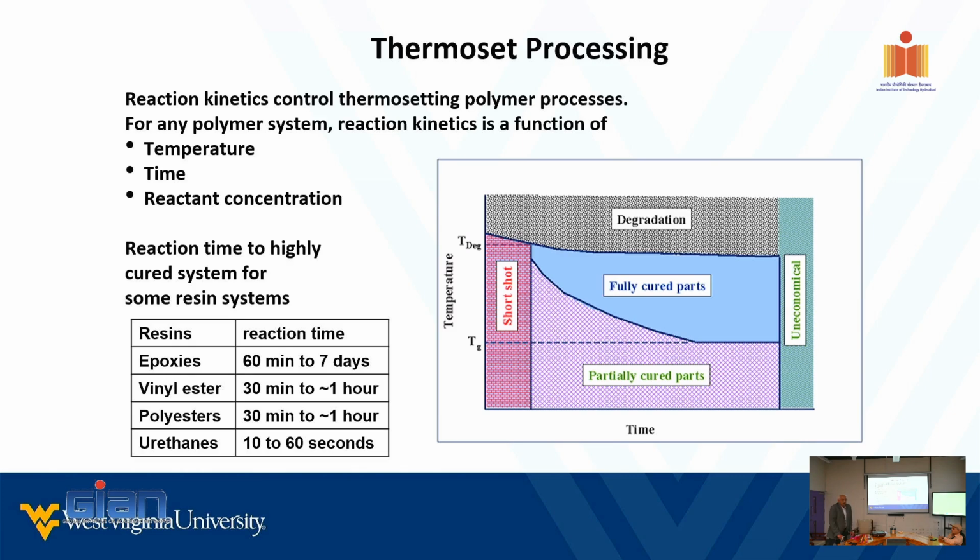But we still put about 10% of Portland cement to be sure. And the beauty of that is we are using recycled material, 60 to 70% of fly ash, and it's a different chemical mechanism, unlike the way your 1-2-4 mix or 1-3-6 mix of a concrete. But that's a different topic. I'm not going there.